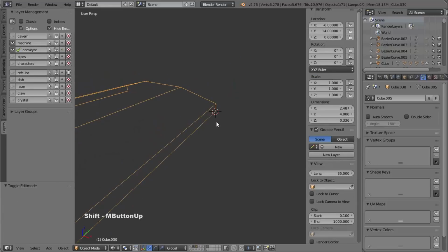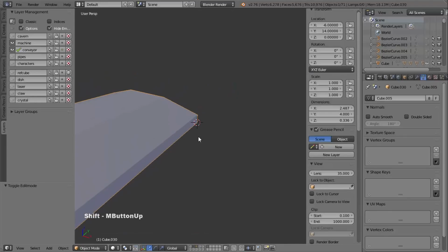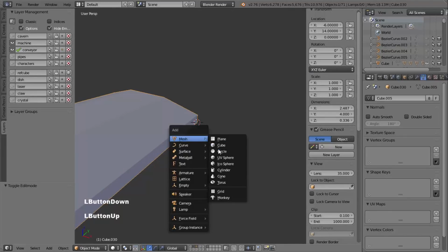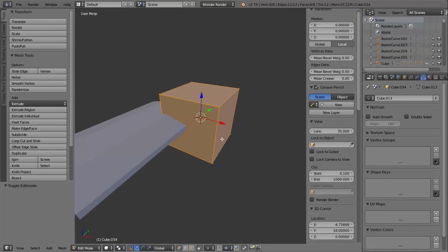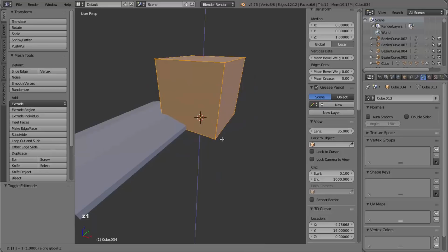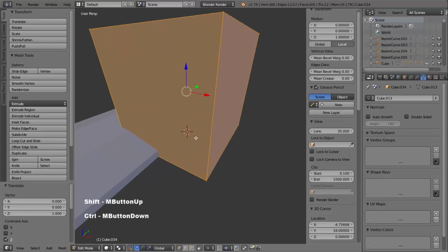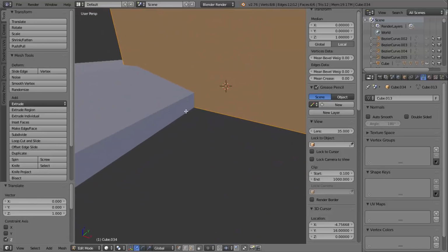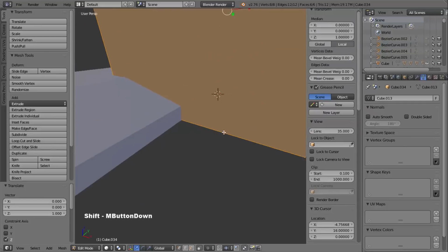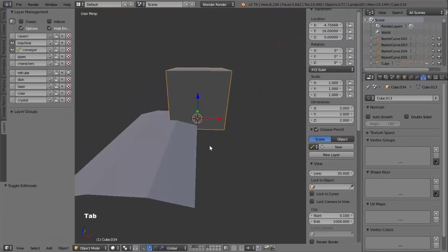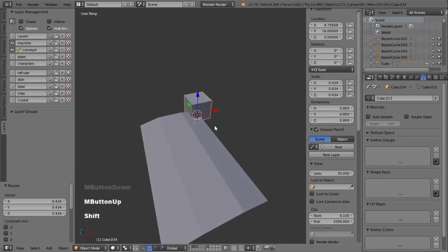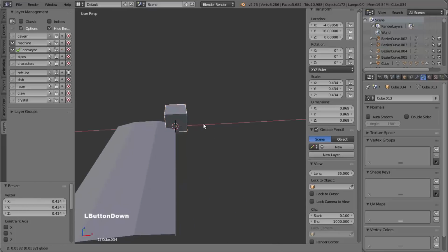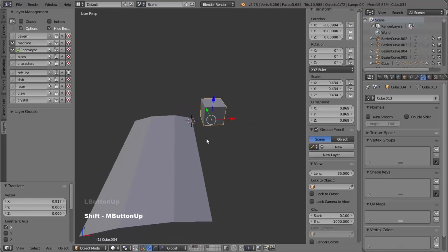And so back in object mode, I'm going to go into solid view. I want to press Shift and A and create a new cube. And then in edit mode on that, I want to press G, Z, 1, and that will place the geometry of the cube nicely on the floor so that it's flush with the level that the conveyor belt is at. So next I want to go into object mode and then scale this down so it's a more appropriate size. I think something like that. I can always change this later. And I'm just going to move this away from the conveyor belt track.